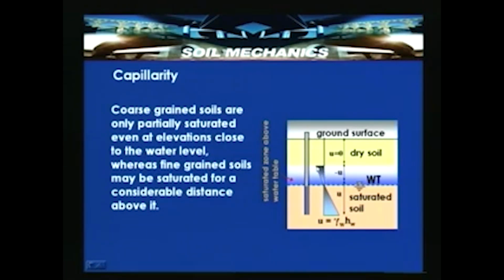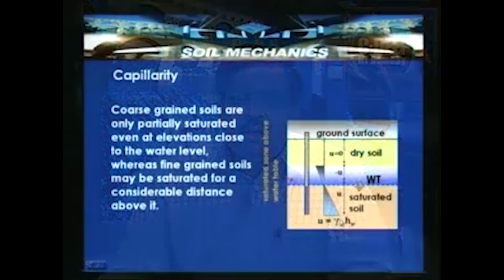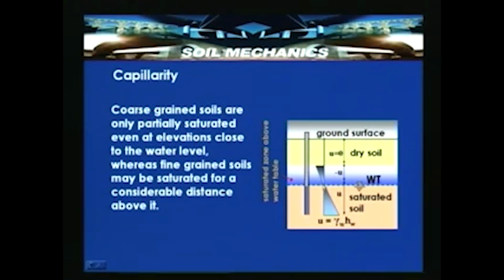The water column which is drawn and kept within the pore space against gravity above the water table is said to be in tension, and the water below, in hydrostatic conditions where no flow is occurring, is under compression. So, the water above the water table is under tension, called capillary tension, and below is positive pore water pressure.